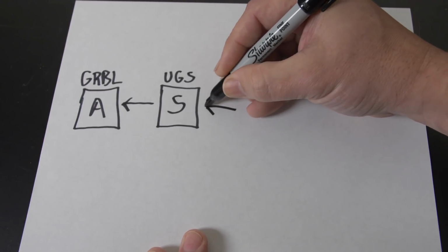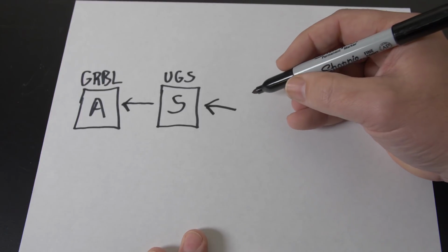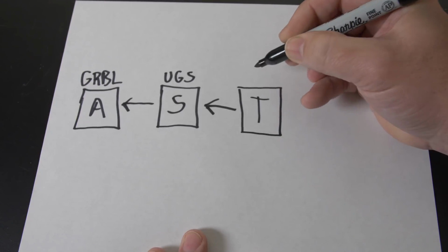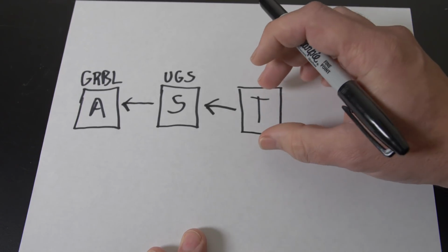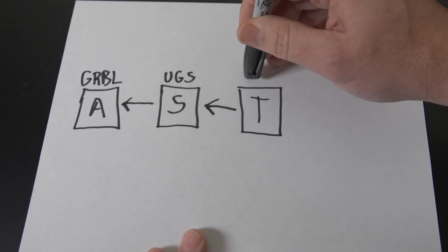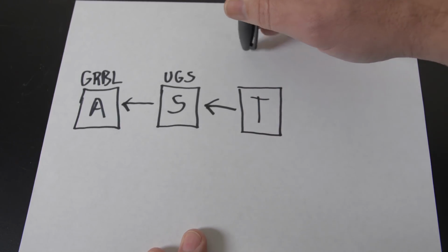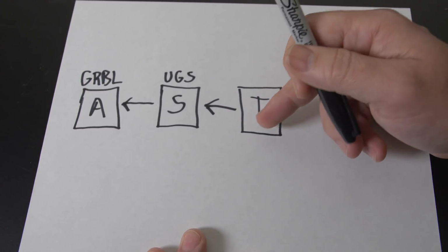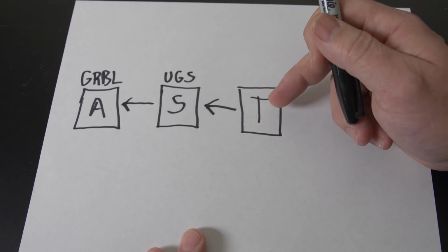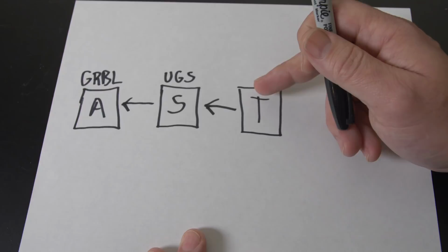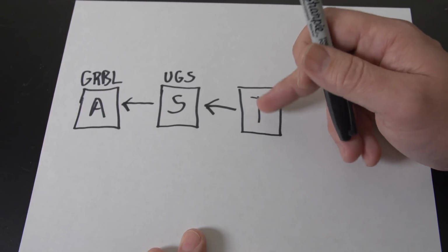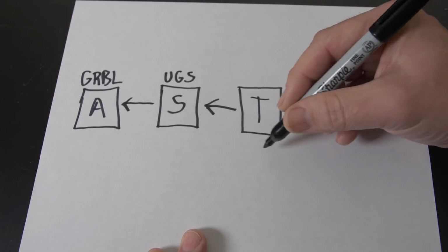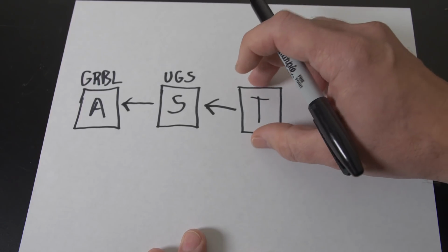Now, next up the stream of programs is going to be the toolpath generating software. This basically creates a list of movements. Move X 10, move Y 10, move X negative 10, move Y negative 10 would draw a square, which would cut out a square. That would be a simple list. You could program that simple G-code list by hand, but we don't want to do that. We want the computer to come up with all of the complicated toolpath lists for us. So this is something we're going to have to come up with. How do we write those toolpaths?